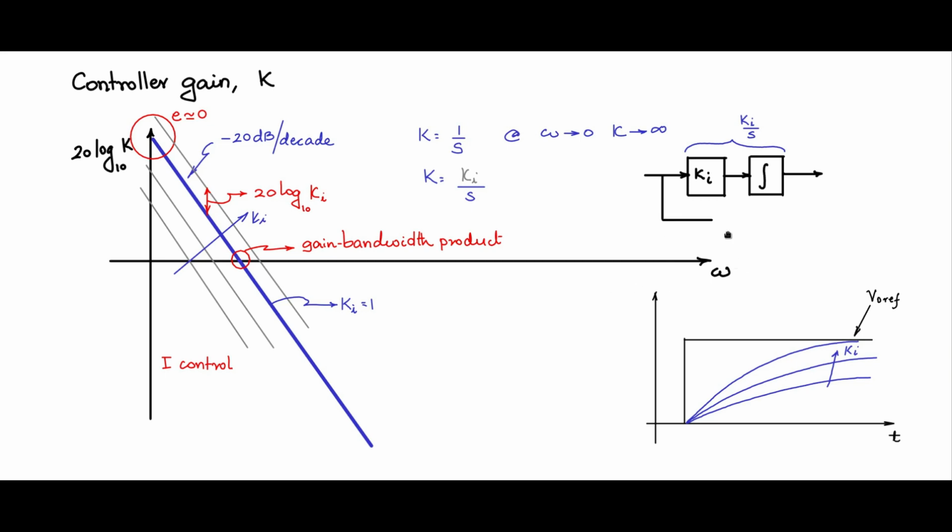Then let me now introduce one more component in parallel. I'll call that one Kp, just a proportional gain, and this proportional gain is added to the integral one also. So you add it up in this fashion. So this is the error, and this is the control signal. Now together, this is Ki by s plus Kp, the transfer function between Vc and E. This can be written as s in the denominator, Kp into s plus Ki by Kp. So you see that there is a zero coming into the picture.